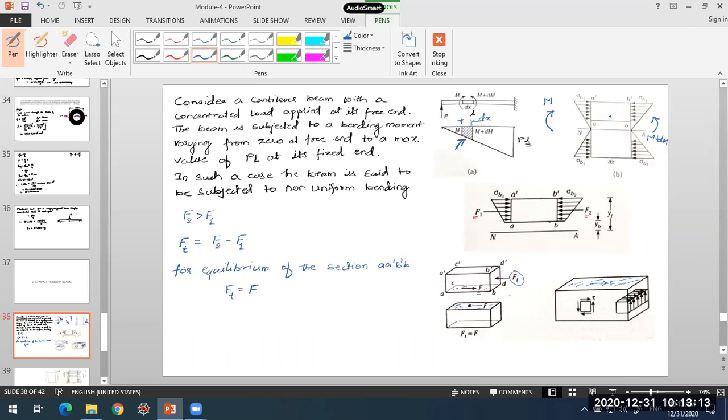So these are the bending stresses acting on our cross section. In this, I have taken the top part of this section, A dash, B dash, B, and shown it over here. Let us look into this. The maximum bending stress is sigma B1 on the left face, and on the right face it is sigma B2. What happens under this situation? There will be two forces acting, F1 and F2. On the left face, the force acting is F1, a horizontal force acting along the length of the beam. Because of the bending stress on the left face, F1 is the force, and on the right face, F2 is the force.